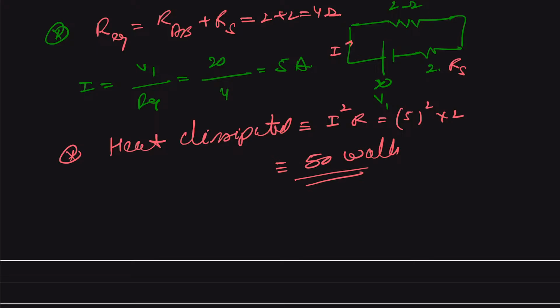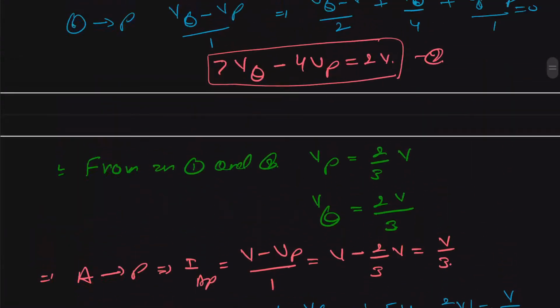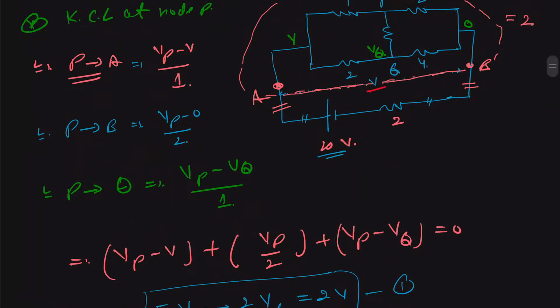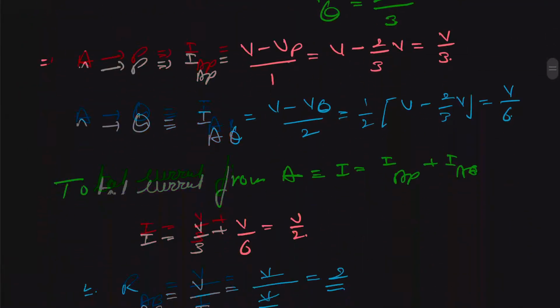And there was some doubt in this question whether the bridge is balanced or unbalanced. But anyways, if the bridge is balanced, that is comparatively easy, and if it is not balanced, then we are going to use this node method to find out the current. And in this case, just remember that to find out the R equivalent, we have used a hypothetical voltage source V, and later on that V just cancels out.